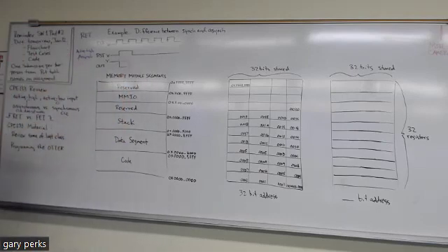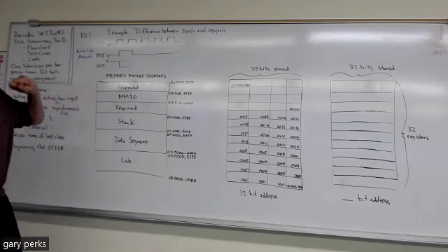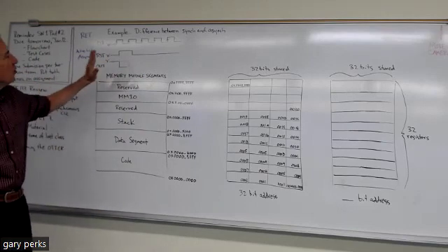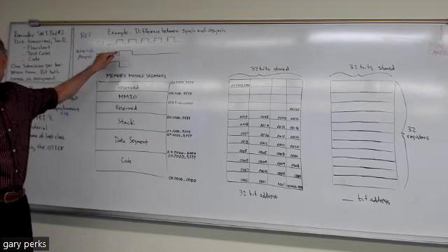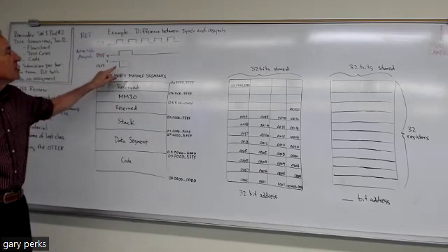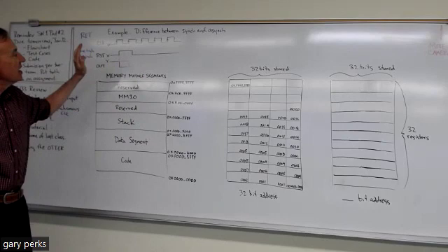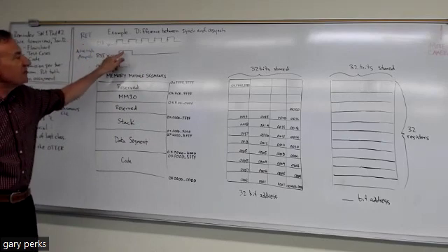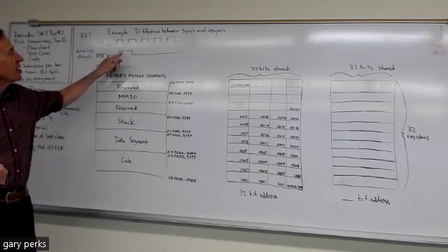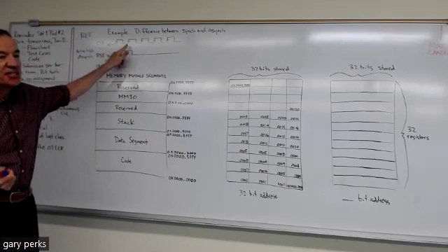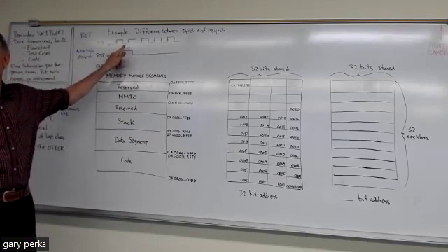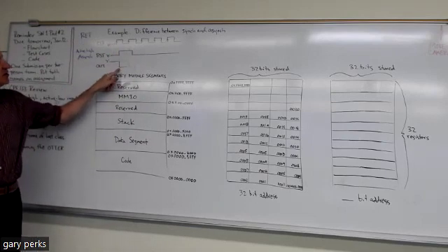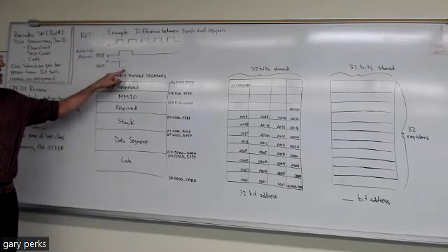This example shows the difference between synchronous and asynchronous. See, with asynchronous, once that input becomes active, it's going to happen. With synchronous, it's not enough for the input to become active. It has to be active during the time of the appropriate transition of the clock, which in this case is the 0 to 1 transition. So you see, this is when it would reset in the async case. This is where it would reset in the synchronous case.